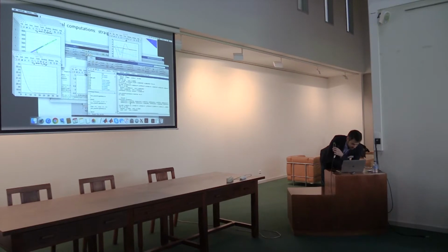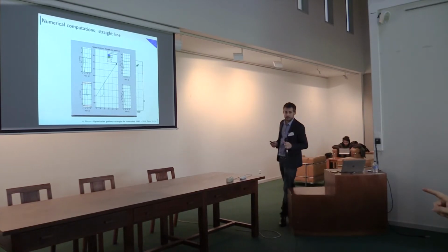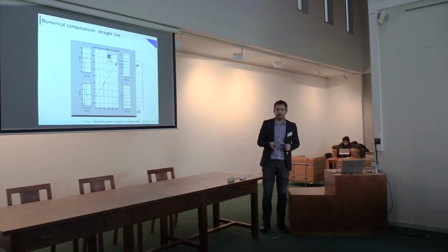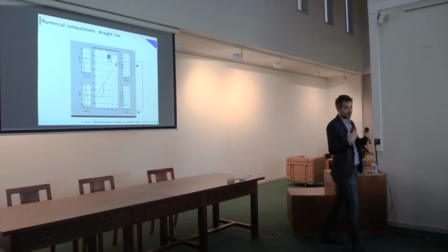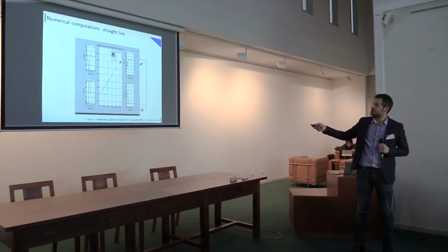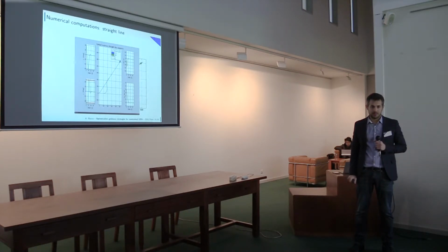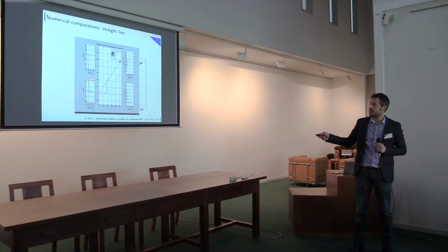So I'm going to stop this now. At the end, we get the optimal trajectory of our UAV model. The green line, and the position of our virtual vehicle, the blue box here, along the desired path, satisfies the dynamics of the vehicle and the constraints. Exactly. You see, this is the roll angle. It satisfies the constraints, and probably also there are some constraints here for the airspeed, for the thrust, and so on.